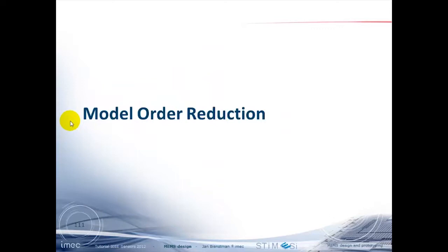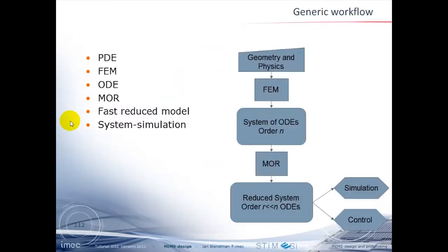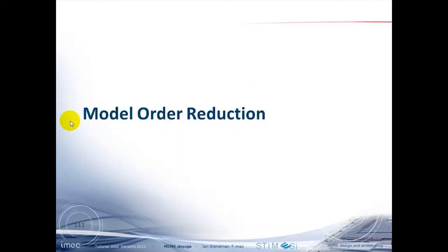This brings me now to reduced order models. Why do I mention it? Well, one of the disadvantages of the behavior models provided by the software vendors is that you're limited to the blocks they deliver. At IMEC, for example, we also did some research on timing devices, and in CoventorWare you have beam models with flexural freedom, so you can make flexural oscillators. But for a breathing mode, the block was not provided, so you're blocked.